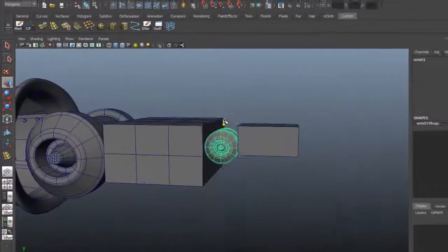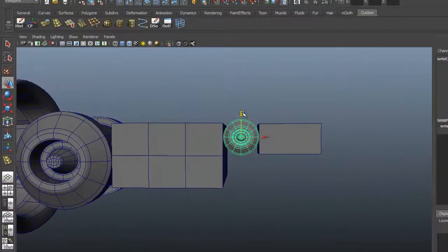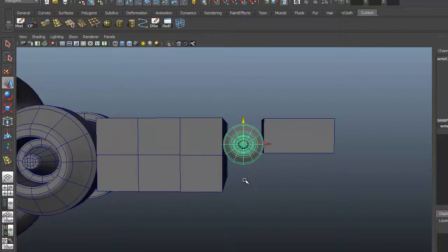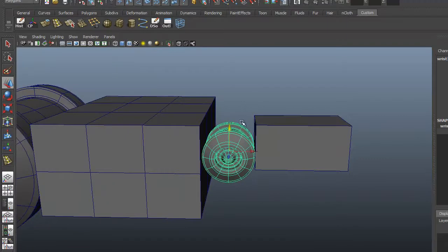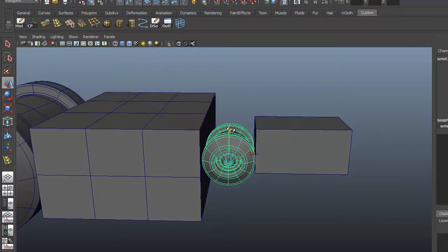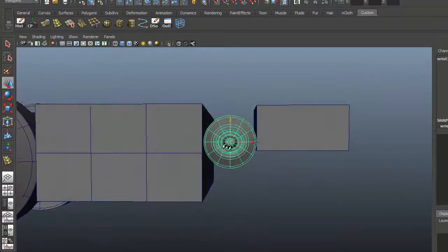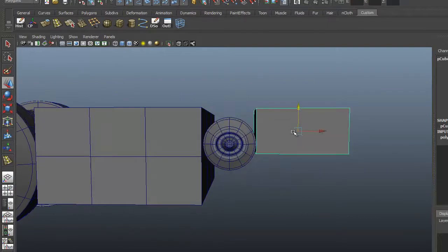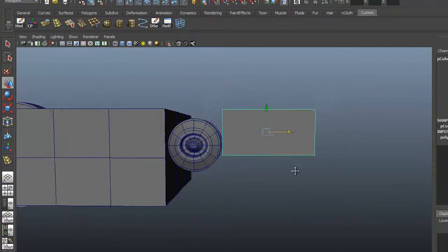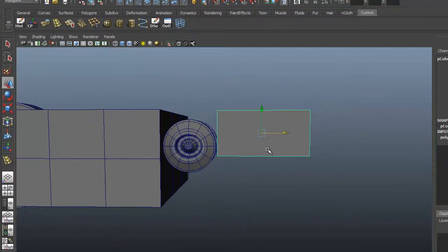We've got to move it up a little bit. I'm going to tuck it in underneath here. We're going to actually have a knuckle sitting on top, made from one of our rivets. So I'm going to drop this down a little bit, move this forward, and let's go ahead and shape this now. I'm going to drop in an edge loop here on the top, as well as one towards the bottom.